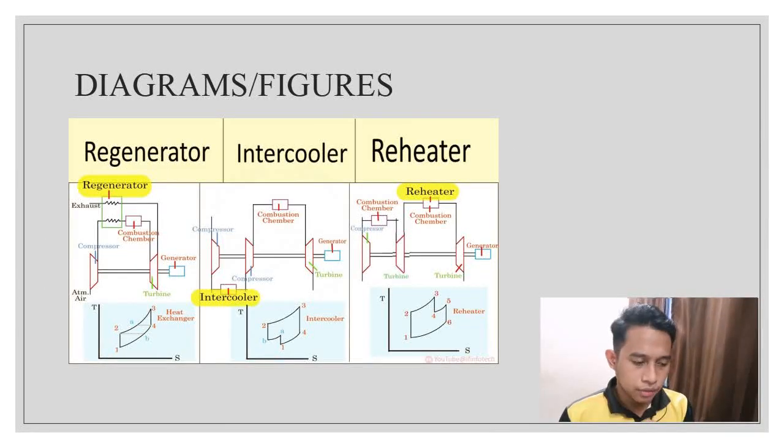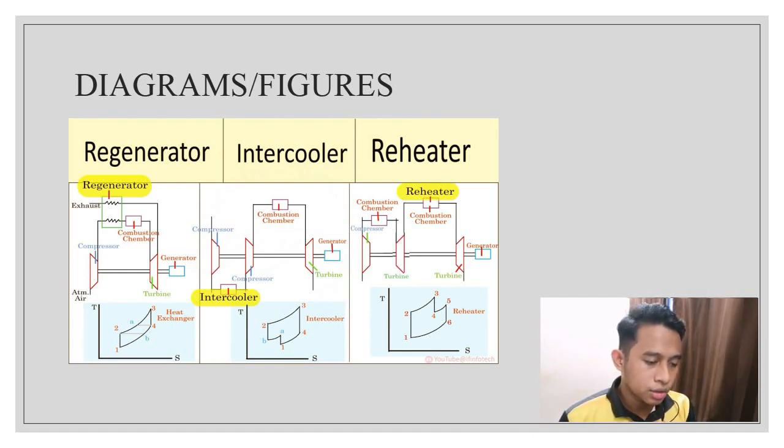My name is Muhammad Arif Hakimi bin Abu Hasban. My matrix number is 01DKM19F1012. Then I want to explain the intercooling. Multi-stage compression with intercooling improves the efficiency of a compression process. A Brayton cycle with intercooling uses 2 or more compression stages with 1 or more intercoolers, as shown below. The power requirement for compression is reduced, but QH is also increased.